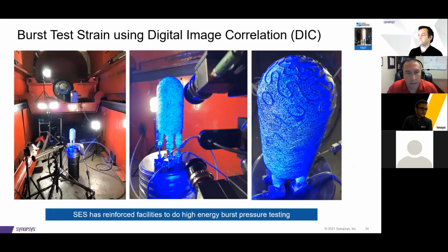During the pressure testing, we were able to monitor the heat exchanger with our digital image correlation system. That system is a pair of stereoscopic cameras that film the test article, where we have applied a speckle pattern coating so the software can track the movements of the test article and relay how the material deforms under a certain load.